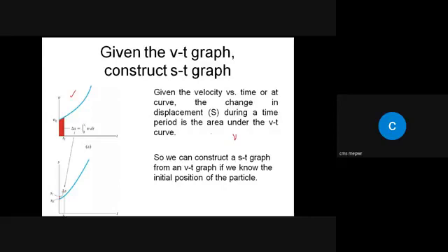and you want to find displacement, you can integrate velocity with respect to time. In other words, the area under the curve on the vt diagram will give us displacement, delta S. If you know the initial displacement, you can find the final displacement within this limit, between 0 to T1. Similarly, if you find the area under the curve in the second interval from T1 to T2, you can find the second point, and so on. You can plot this st diagram, right?